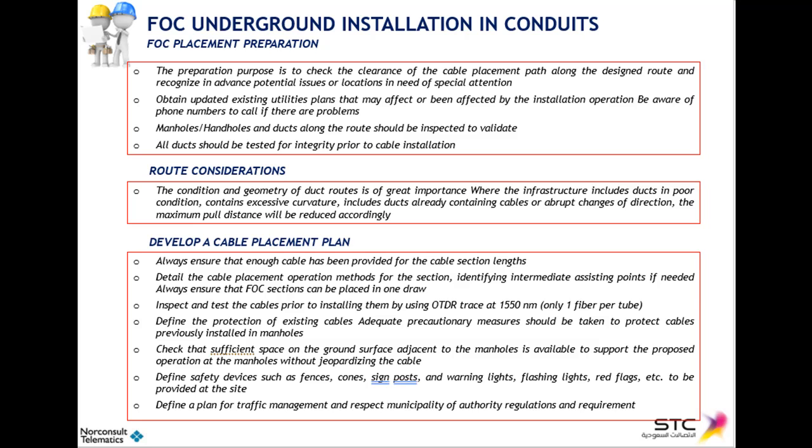That on one side. Then have a look at the geometry of the duct routes, if they are straight or bent, and if they have excessive curvature, try to fix those. You have to plan all those things ahead and try to remove abrupt changes of direction. The last point is to create a cable placement plan before you install the cable. This should be really helpful for you.